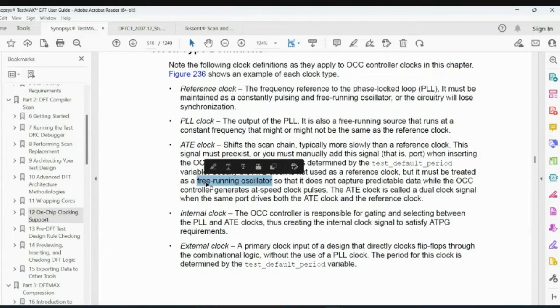So when you get that ripple accidentally, even a ripple can excite the flip-flop, and the flip-flop might take this ripple as a clock and latch the data. That means it might toggle the data. That is very bad for our design.